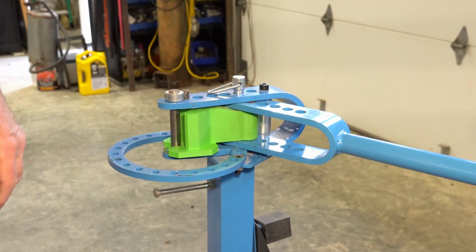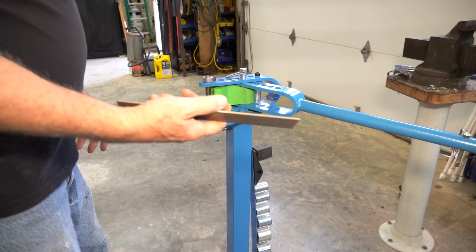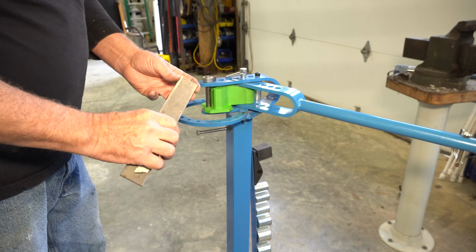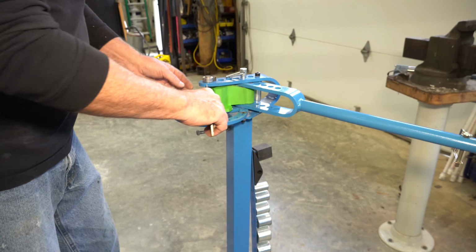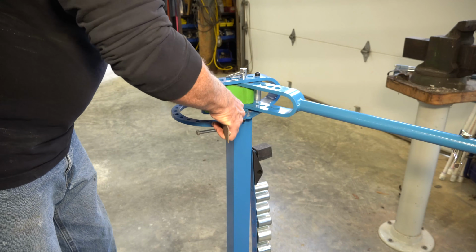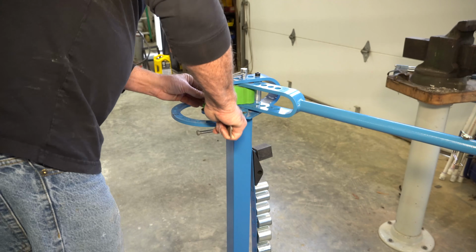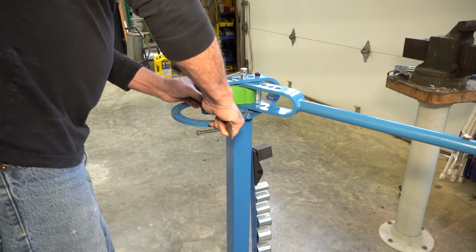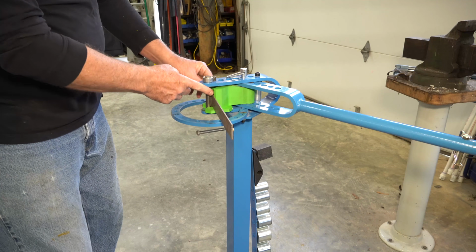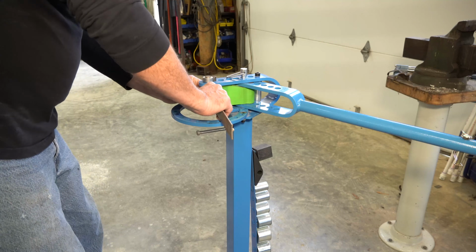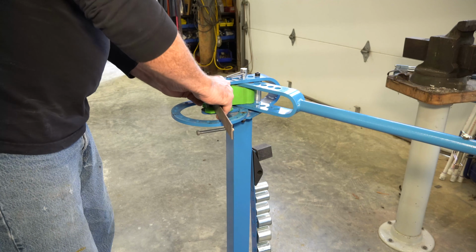I'm kind of impressed. I have a piece of 1.5 inch, 1/8" mild steel flat stock, so I'm going to see how well that bends in there. And I could modify this die pretty easily, probably just take it to the milling machine and mill that off a little bit. So let's see how well this one works.